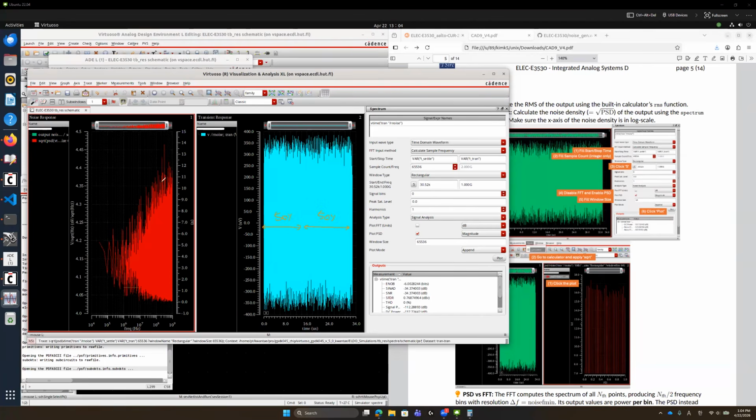Then for running FFT, it looks like random, right? So for running FFT, the randomness will make sure that maybe it will be different like this. Like this. So you can see that there is a peak. But for running FFT, let's say there is one giant peak at this frequency within this window, but in the next window, maybe this peak will be the other way down, like peaking at this point or less peak. Then these peaky data points can be averaged out. So we want to calculate the average baseline of the noise power spectral density. So that is the intention.